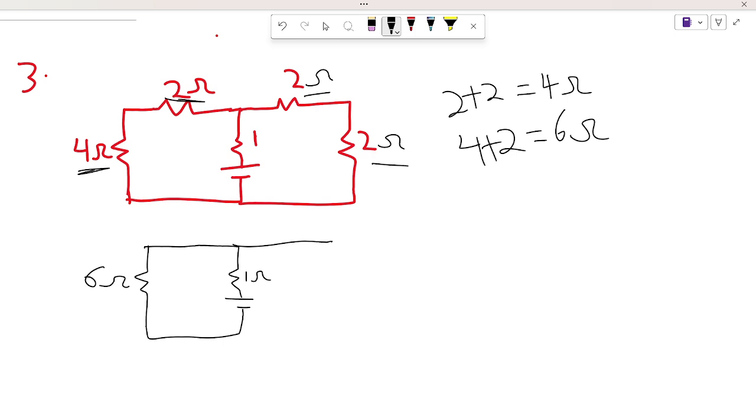So you follow through what we are doing. Here we have 4 ohms present here. Next, you realize that since there's a node present at this particular point, and when you traverse the path between the 6 and 4 ohms, there's nothing else there except the two of them, these two are going to be in parallel.